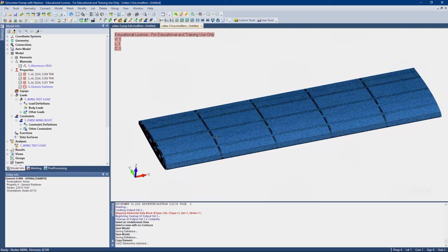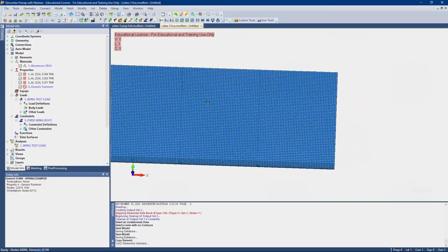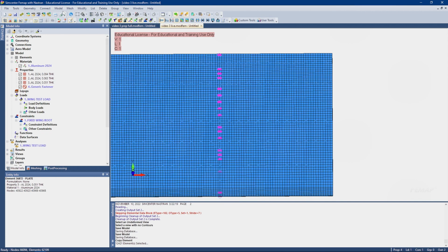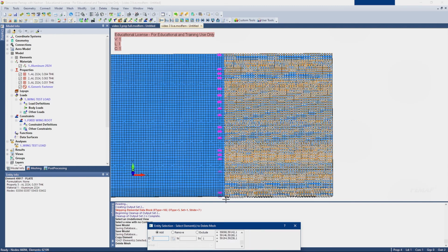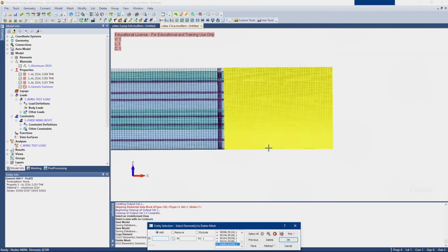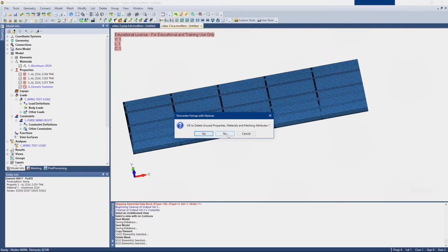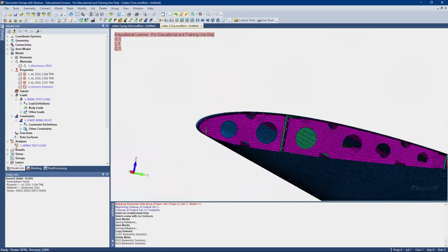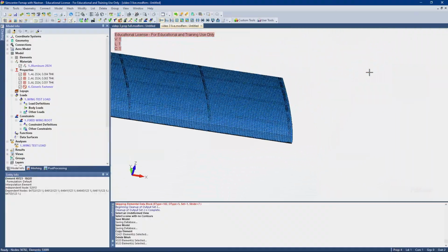And now let's go ahead and come over here, and we'll go to delete model mesh, and just try to select as uniformly as possible. Make sure everything looks good. It does. Then hit OK. Okay, delete unused properties. I always hit no, but there won't be any unused properties. And now you can see, I think we probably wanted to do one more element in, but that's okay. Let's just leave it.